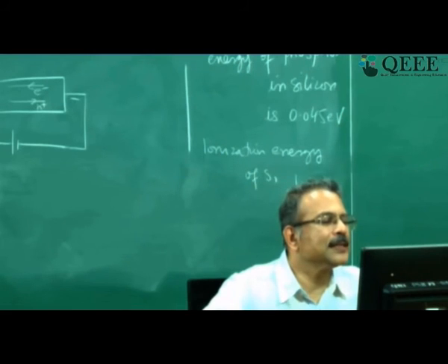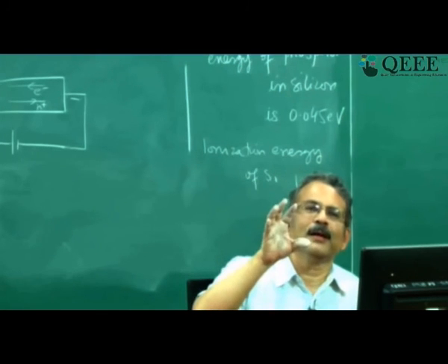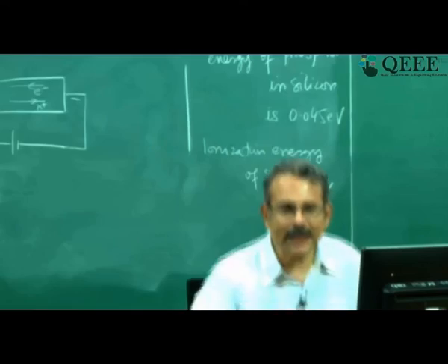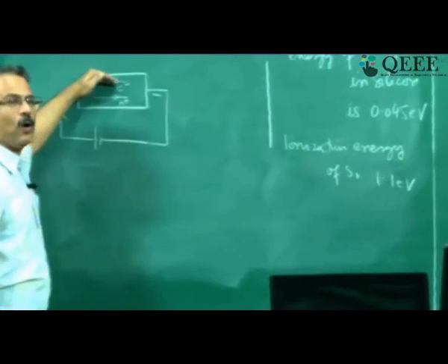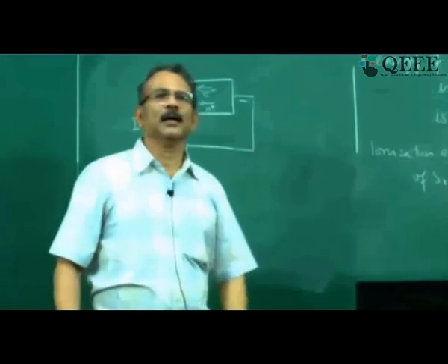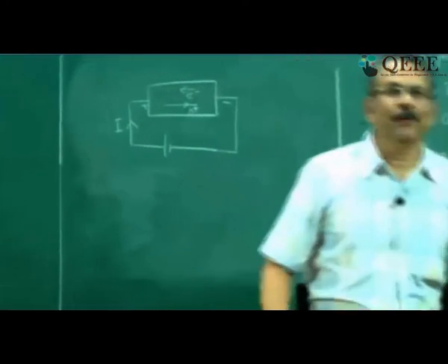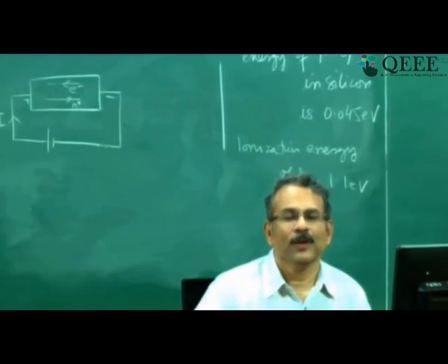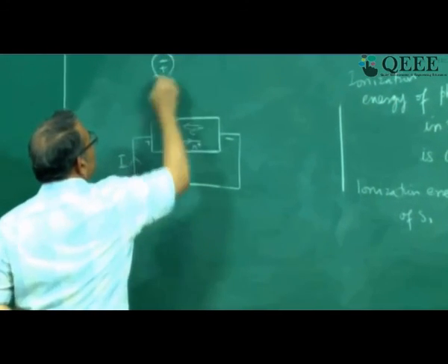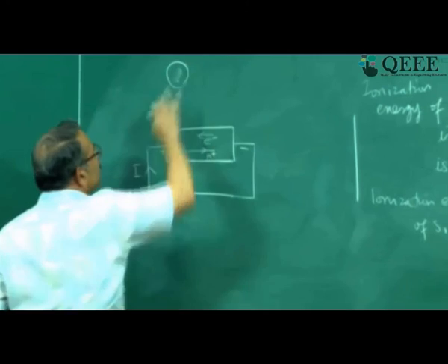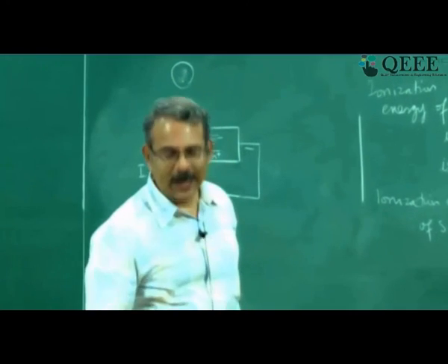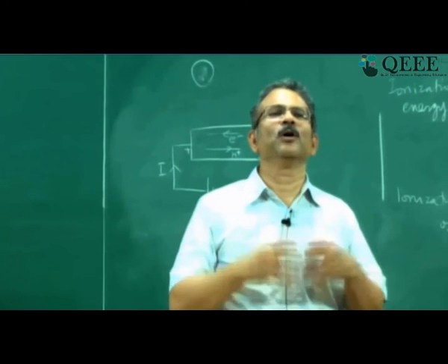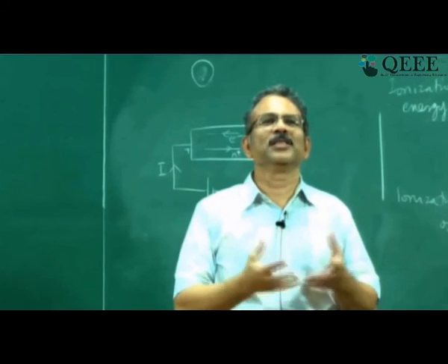Why is the direction of hole flow considered as the direction of current flow, not the direction of electron flow? No. We are considering the electron flow also. As you can see here, when there is a drift, you take the direction of electron flow into account as well. When we come to diffusion, you will see both electrons and holes can move in the same direction, right? But then their contributions will cancel out, okay? Because if this is a negative charge and this a positive charge, both moving in the same direction, you can club them together, and negative and positive together is how much? Zero charge, right? So if electrons and holes are together moving in the same direction, it amounts to no current because together the charge is zero.